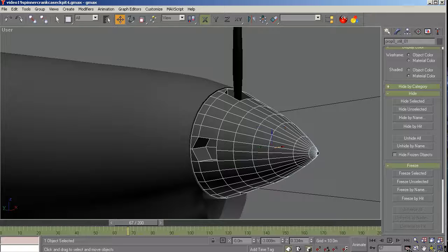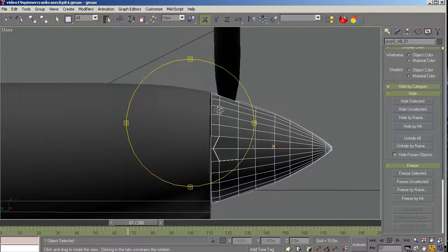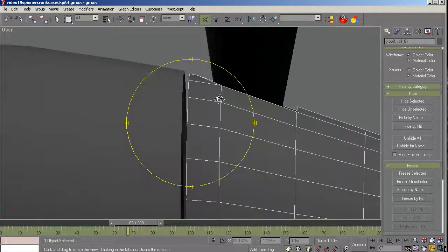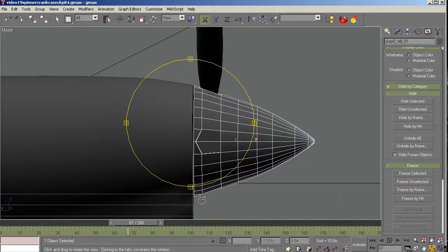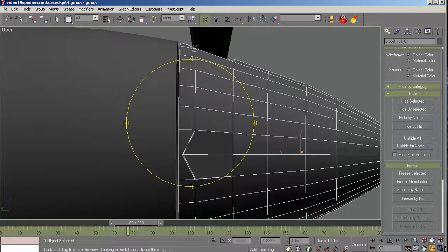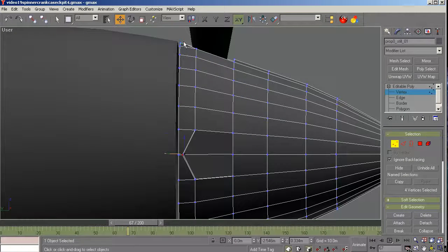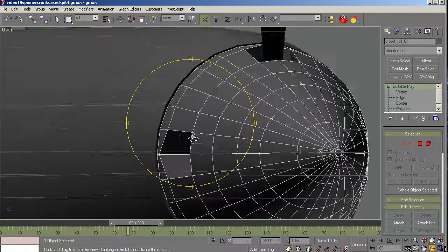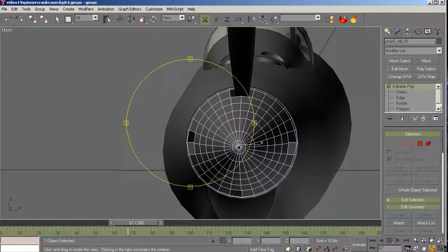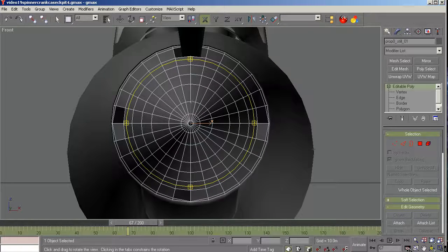Now in doing that, because of the shape of the spinner here, that vertice that was sitting right here is now back here, so I had to grab all 4 of these once the recesses were propagated around, and use a scale tool and just roll those vertices up so they're up there at the correct height and not messing up our curvature here on the spinner. So basically grabbing 1/4 of that. Actually, I'd never done that before on a spinner, so that was kind of interesting.